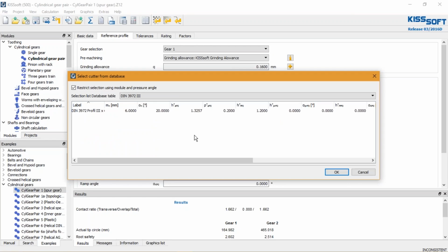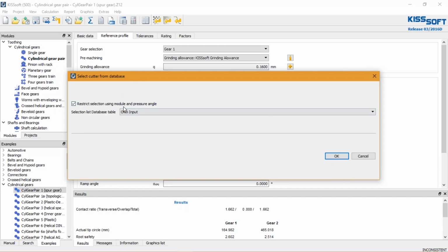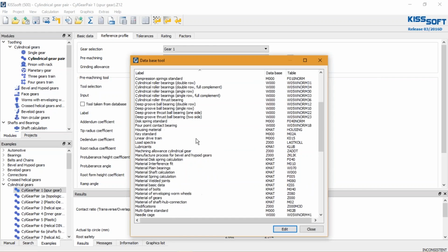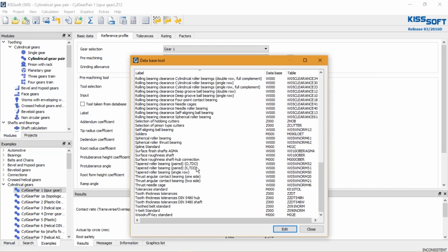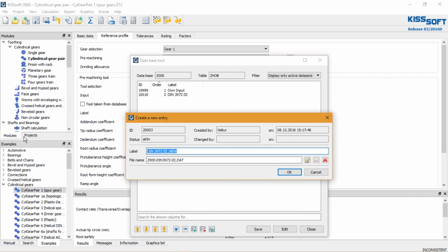And now is an interesting point. We cannot see our defined cutters. Why not? Because in this particular example, number 1, the module is by coincidence 6. And if you have checked the list, we don't have cutters in this, well, for module number 6. So actually I need to recheck why it didn't add the tool. So I'm going to go back there and check selection hobbing type cutters, and actually it didn't work. So I press again on the plus button and try it anew.